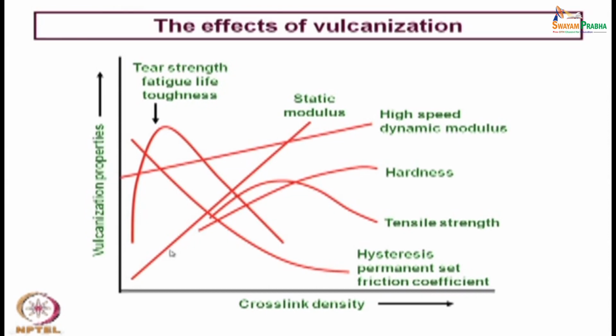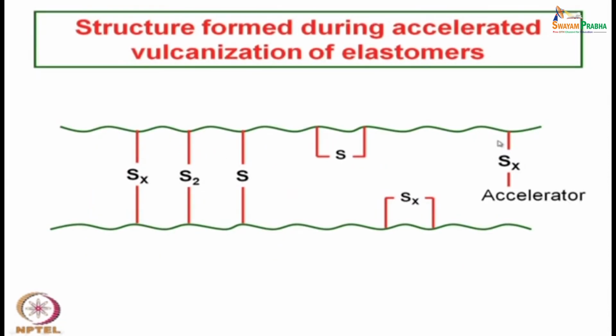So, if you look into the cross-link density, it can be taken as an indication of the property level of that particular product. Which properties are required, this kind of schematic diagram will help to make a proper formulation. Look at the ultimate vulcanized network of the rubber chains.